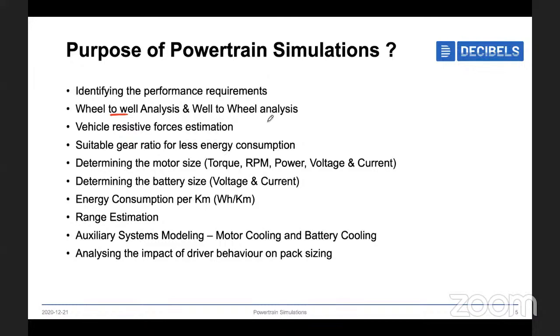Okay. And we can estimate energy consumption. Yes, we have the event called energy efficient event in the formula events, right? If your vehicle is consuming less energy, it means your vehicle is more efficient. So if you want to understand this before going to real time testing of the vehicle, you can develop this powertrain simulation and estimate your energy consumption of the vehicle.